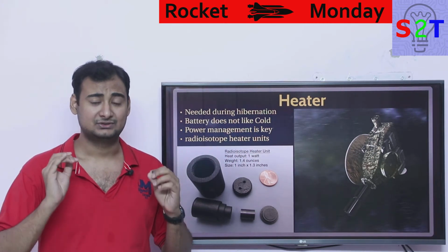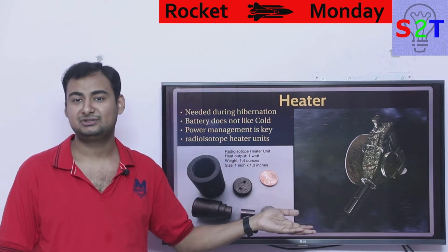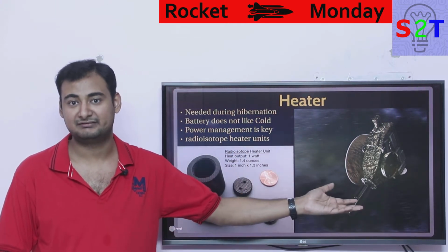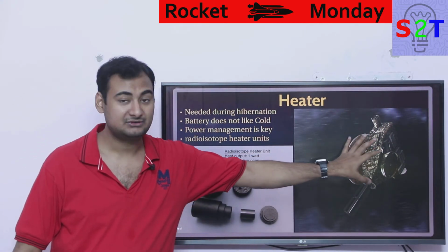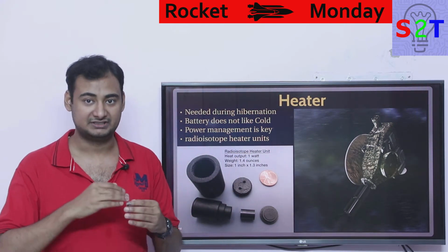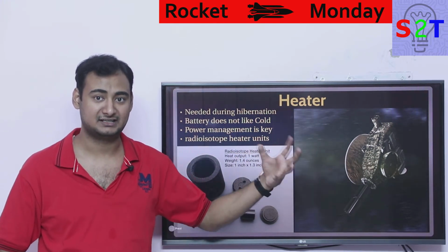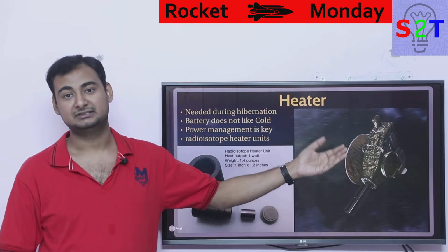So during that hibernation, no computer processor is running, only the radio beacon is running, on minimal power at that. So whatever energy source you have, let's say this RTG, even though it's giving you 500 watts of energy, you're not using it. So it's just like disconnected. That means this part will freeze. Even though it has insulation, no insulator is perfect, and it's not like a human body, which has 100 watts of continuous power. So during that off period, the temperature goes down.